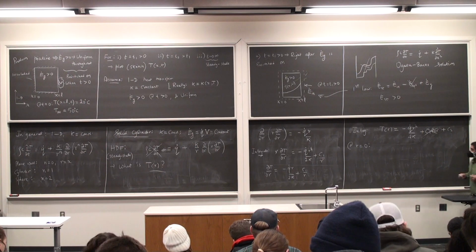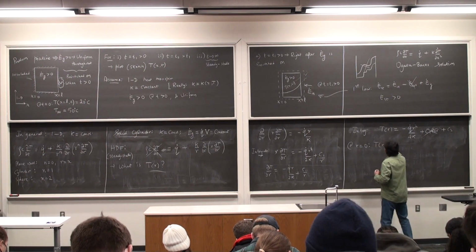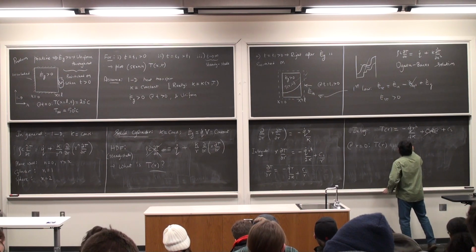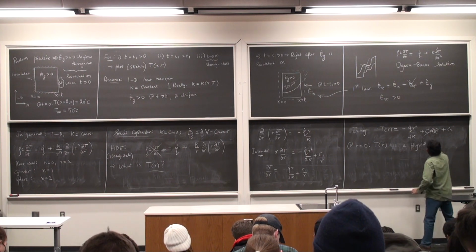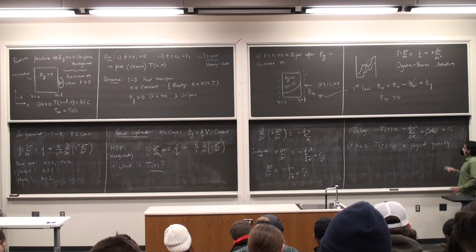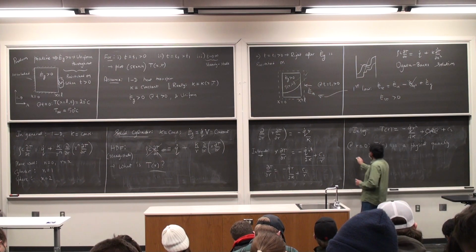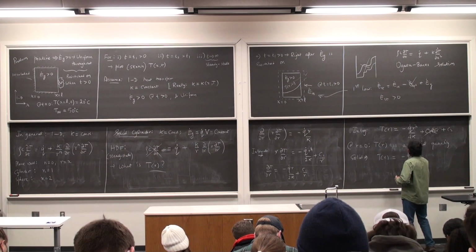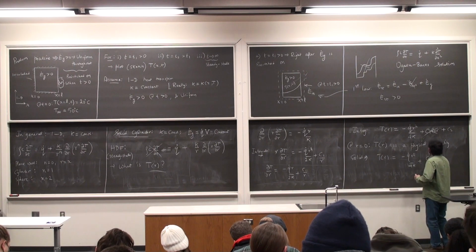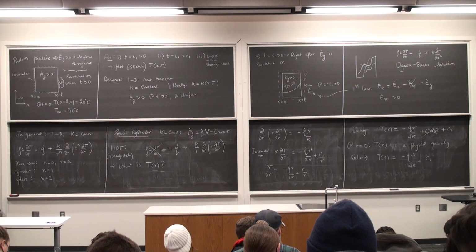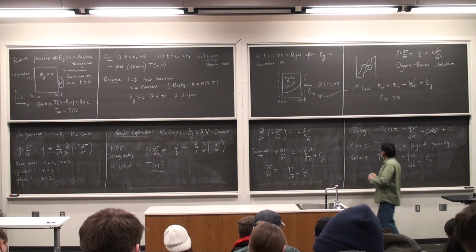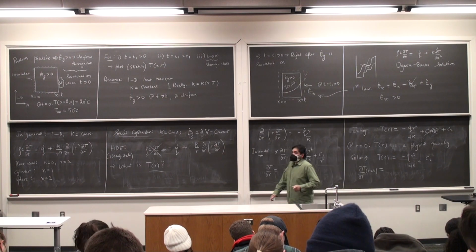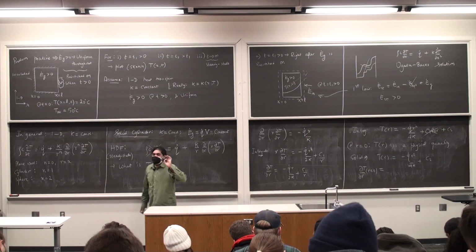So if I have a solid cylinder, c1 is 0, and T of r for a solid cylinder is minus q dot r square by 4k plus c2. This tells me that if I take the derivative of T at r equal to 0, this derivative will end up being equal to 0.